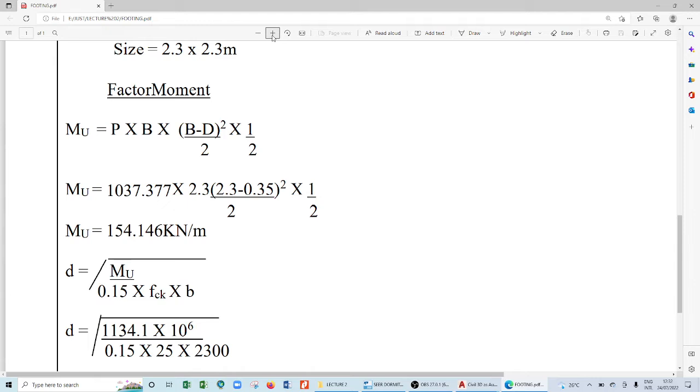So if our concrete cover is 50, and this is what I'm having, so if this bar is going to be D16, it is on the side of that bar, we get a half of that diameter plus the concrete cover. So if it is 16, I'm going to say 16 divided by 2, which I get 8. 8 plus 50, you want to get 58.